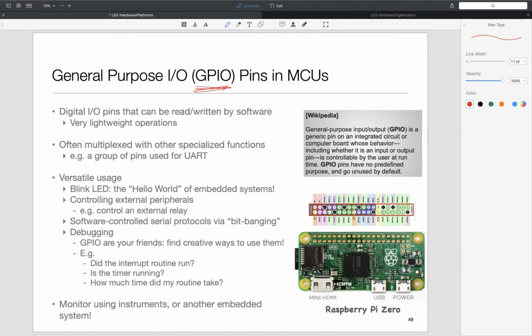One of the advantages of these embedded processors is that you can do very precise timing. If you want to generate a specific waveform to control the rotors on your drone, you could do it. It's called bit banging. I can do bit level precise timing by making use of low level software and real-time operating system features.